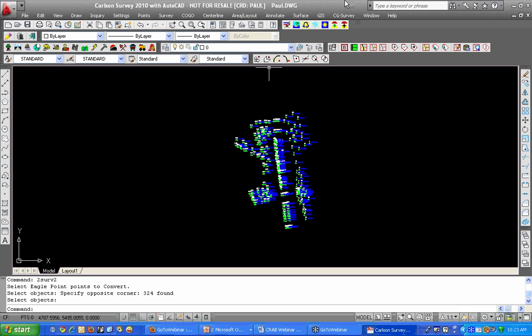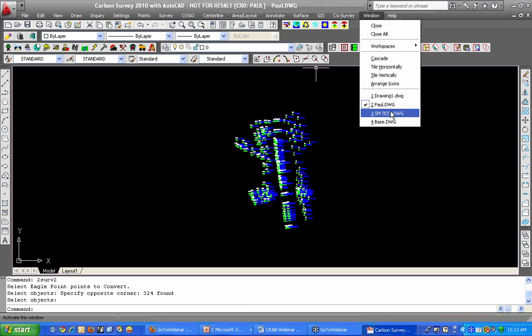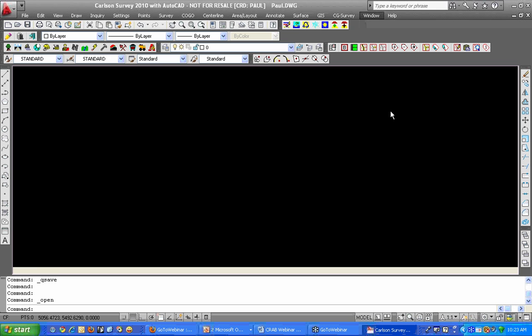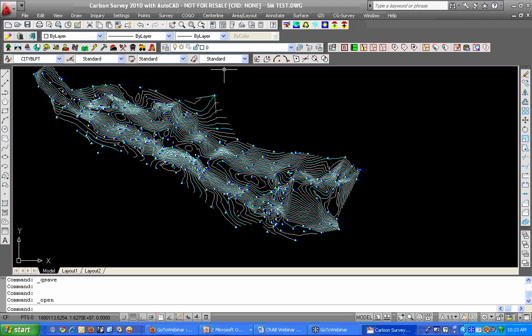Point of interest possibly for anyone out there that may be using Carlson SurvCE in the field to do their survey. This coordinate file, CRD file we're talking about, that is the exact same CRD file that's used on the data collector. So that goes back and forth seamlessly. So we can go ahead and jump between drawings, but the interesting thing is the software actually keeps track of where you are, so it knows what folder it should be working with.